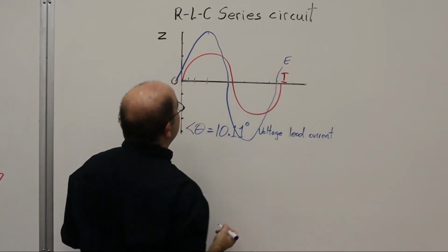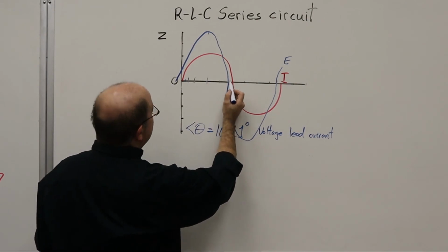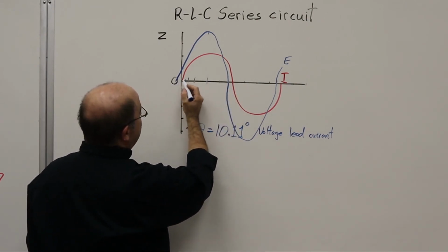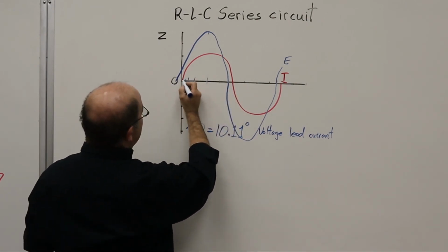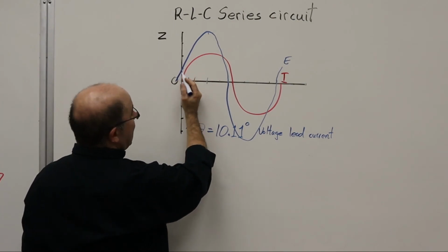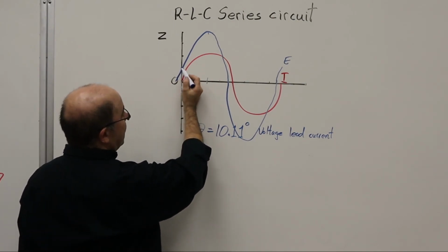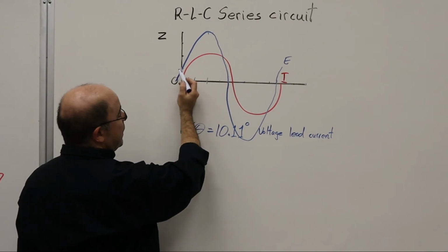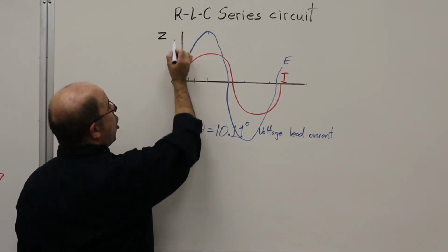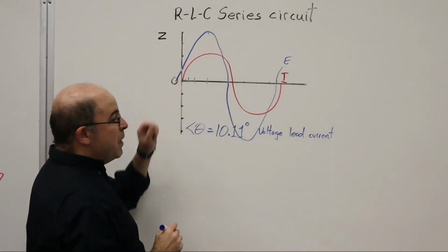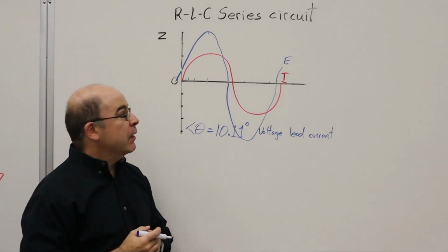I'm going to identify it because the phase angle difference is right basically here. If I drew the straight line, the voltage is ahead of the current. Not by much, but it's there if I follow this line all the way up. So this is what is meant by that leading power factor.